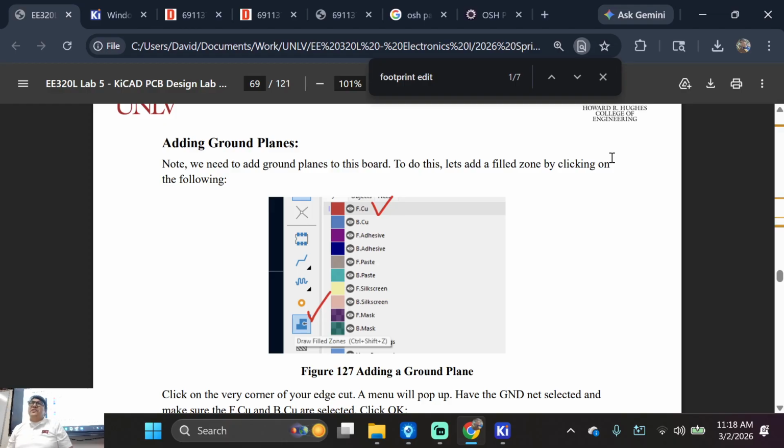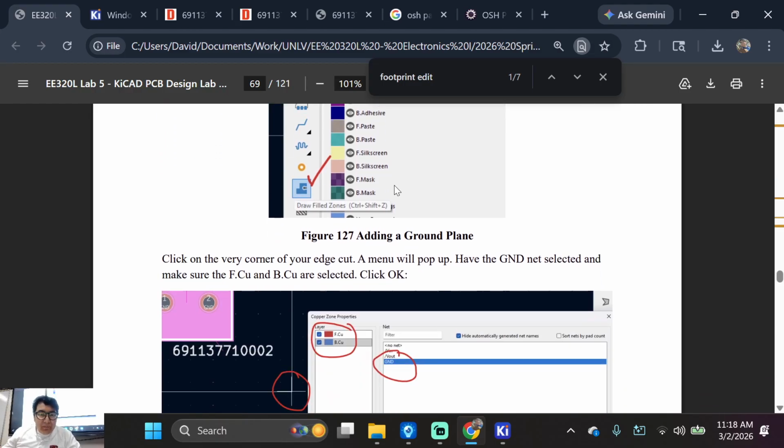If you're a power team that's dealing with like a million or like an amp of current, I don't think you need to worry about it. If you're building a drone, don't worry about this either. Because we had someone build a drone with this application. It was really cool. They did like this cool shape. And I was like, don't use a ground plane. It's going to make your drone too heavy. So just use really thick copper wires. So you can do a lot of cool things. But for this class, I want everyone to do a ground plane, okay?